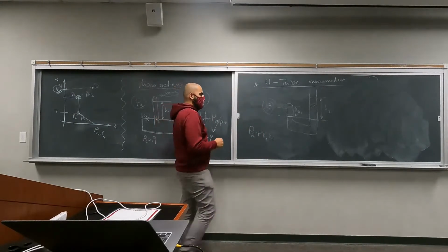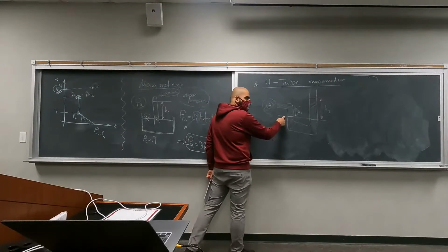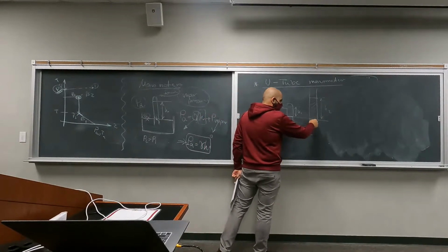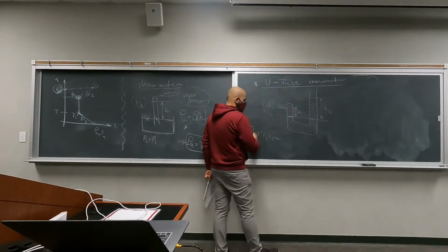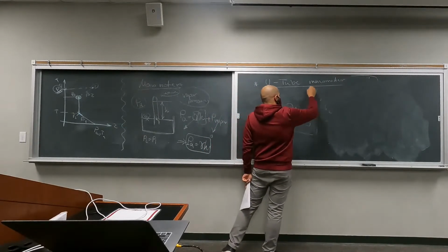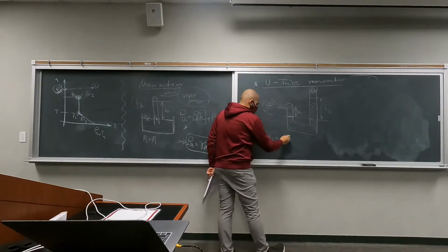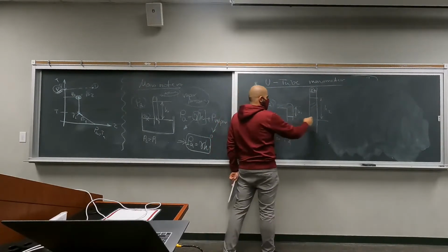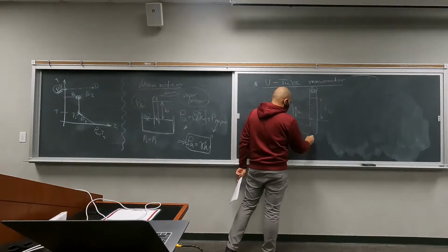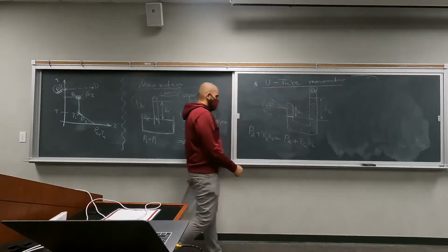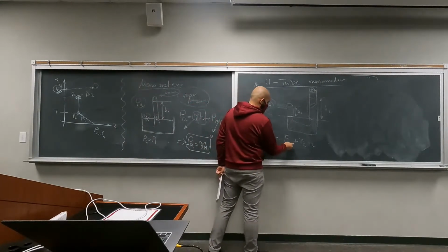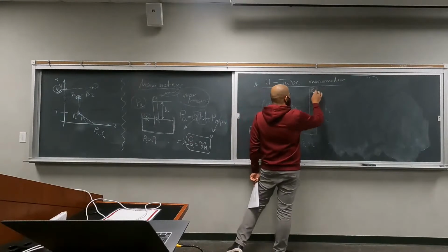It has to be equal to the pressure at this location, at this height, which is equal to the pressure at this height. So the pressure at this height is the atmospheric pressure, whatever that is, plus gamma 2 for this liquid, H2. Let's call this P0, atmospheric pressure. We don't want to use two A's.